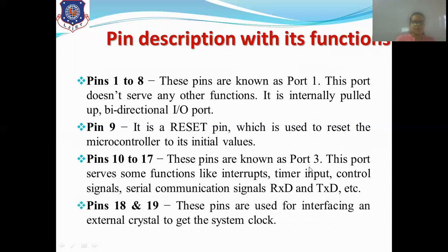Okay, next are pin 18 and pin 19. These pins are used for interfacing an external crystal to get the system clock. As we have discussed in the architecture, the 8051 controller has a crystal frequency of 12 megahertz. So on the XTAL2 and XTAL1 pins, which are pin 18 and pin 19, there is a clock circuit in between which generates the 12 megahertz frequency. How the clock circuit is generated, we will see in the next session.